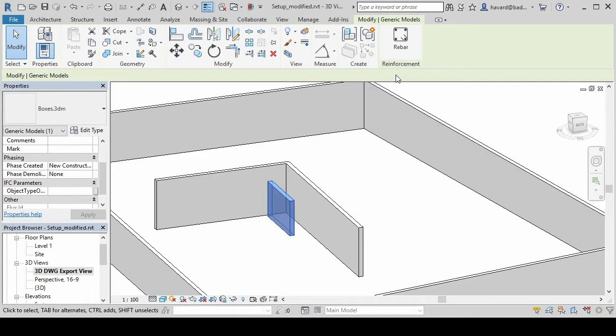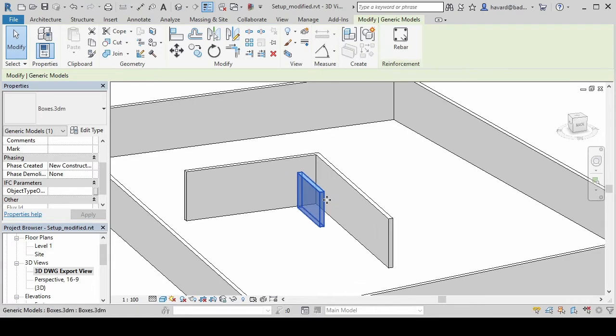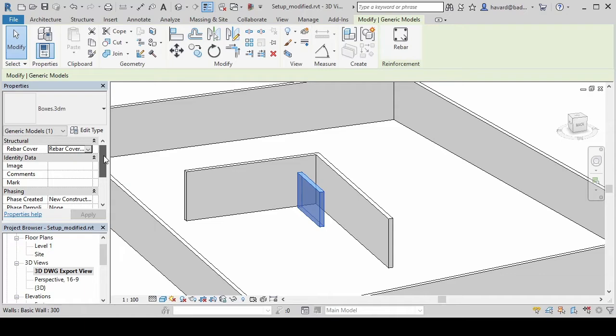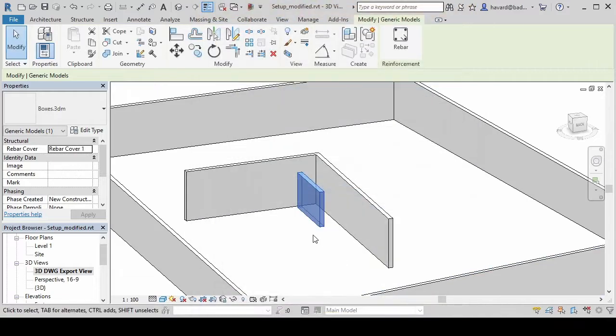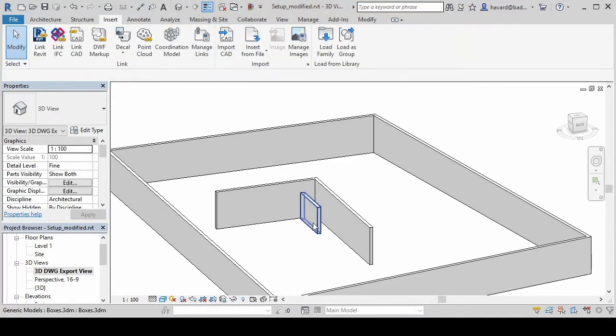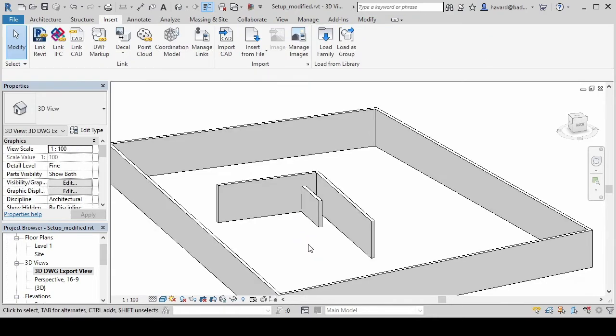It's a box. You can put rebar in it, and that's basically it. You can copy it and rotate it and so on, but of course we prefer to do that in Rhino. If you're going to keep designing this element inside Rhino, it makes sense to just keep it as it is in Revit. You have access to some instance parameters and some type parameters, but very limited. Maybe most importantly for architects is that you don't have any ability to override the material of this element.